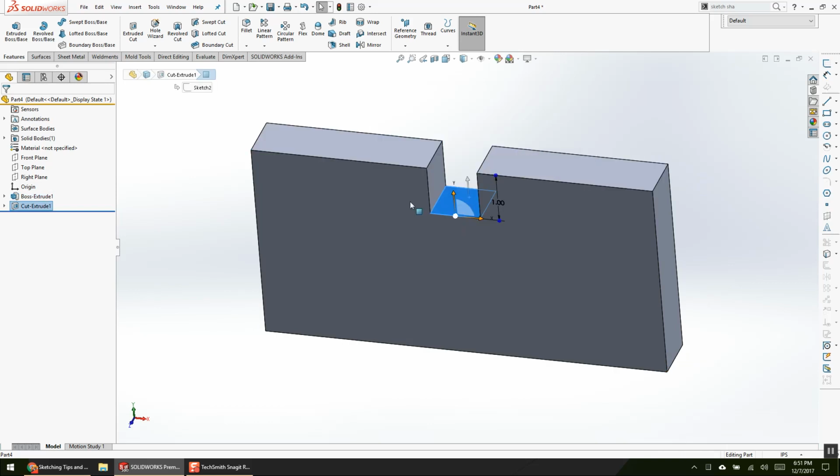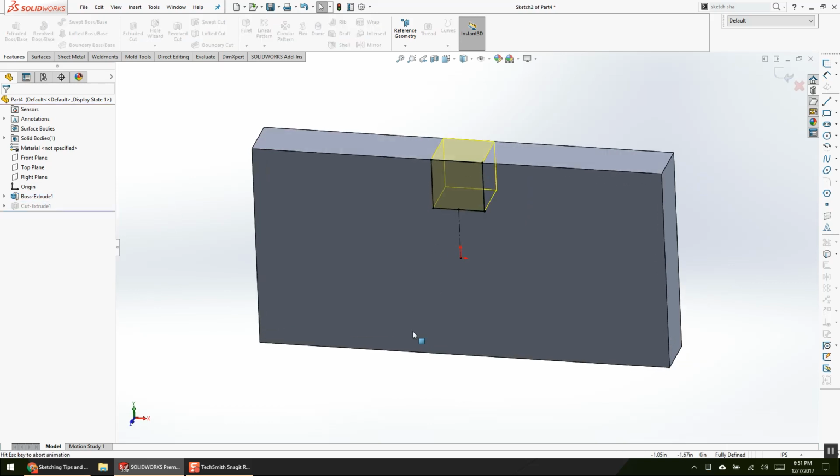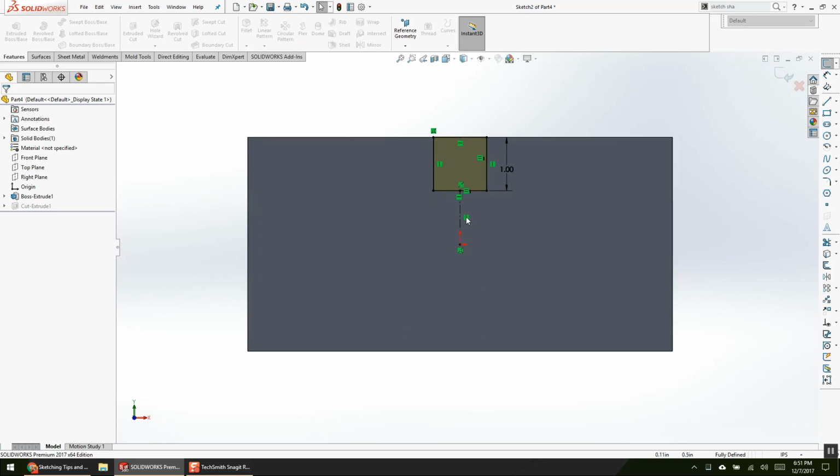So that's what I would do there. And to belabor the point somebody else mentioned about our drawing, in no way, shape, or form is that one dimension helpful, valuable, or complete for a 2D printed drawing for manufacturing. But in no way am I going to be inclined to add more than one dimension to fully define my cut based on the design intent I'm trying to accomplish. So I'm not going to go out of my way to make my 3D models worse to have a dimension show up on my 2D print that I could easily add on the 2D print in isolation.